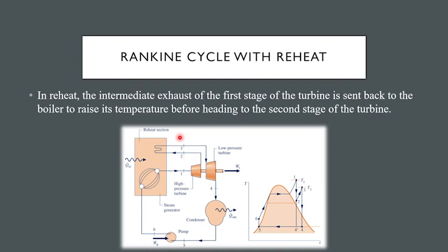We simply added reheat steps, and we have divided the turbine into two distinct parts, the high pressure part and the low pressure part. If we look at the temperature entropy diagram, stream 1 is already a superheated steam. After passing through the turbine, this is an isentropic turbine, its temperature drops to T2 in stream 2, and then by inserting stream 2 in the boiler, we are able to increase its temperature from T2 to T3. From stream 3, this then enters the condenser and then the pump and then the boiler. And the cycle repeats itself. So the modification for reheat is only in this part.